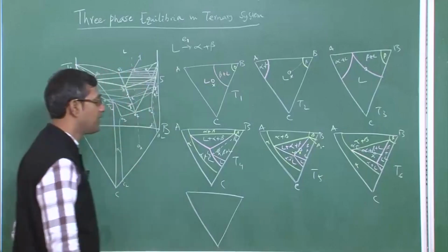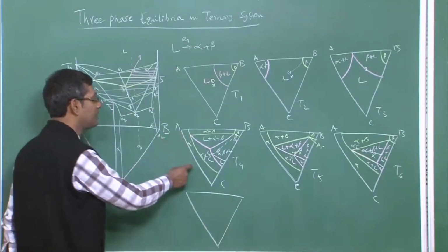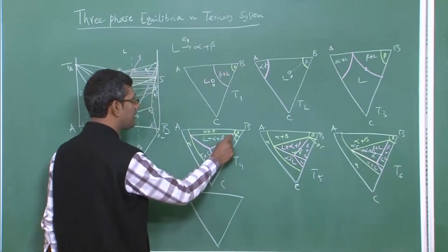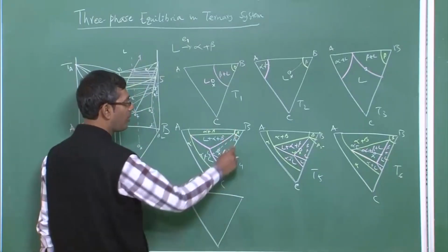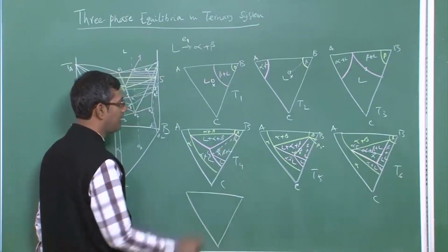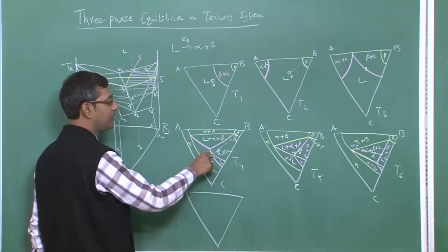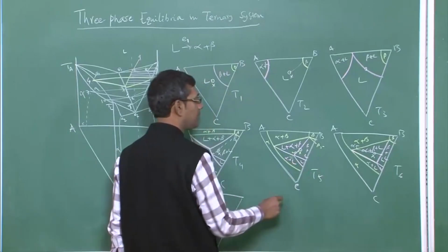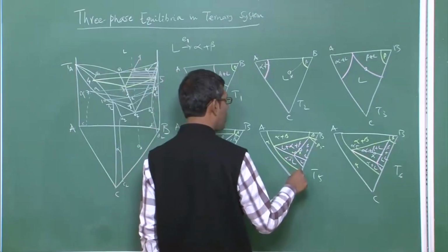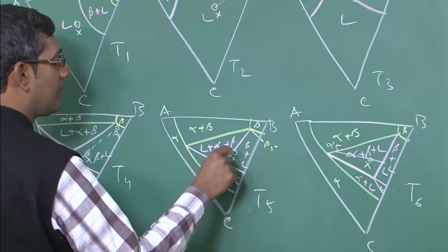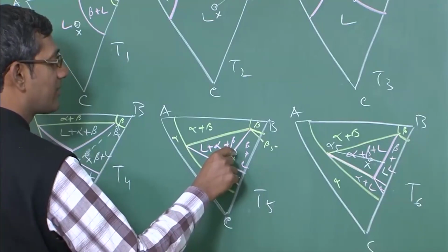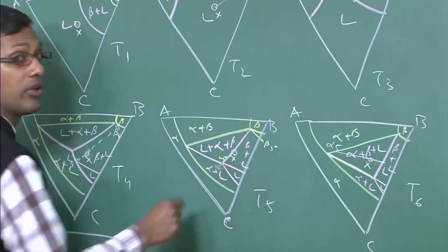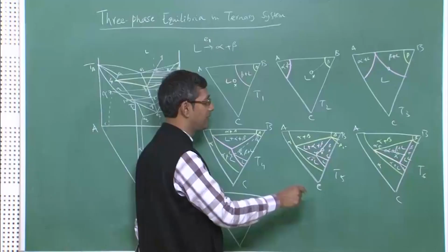So, the thing which is clear to you is that at temperature T4 it was precipitating only beta, and beta composition was B4, okay. And this composition of beta was in equilibrium with the liquid composition of L4. At T5 the temperature has dropped so much that the alloy composition is sitting on x, on the boundary between the two phase field and the three phase field, correct.